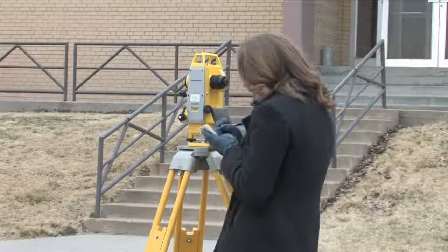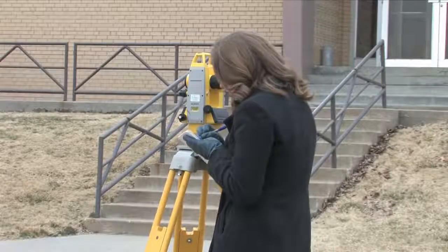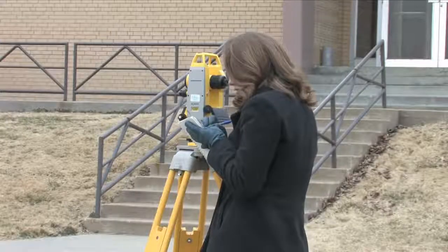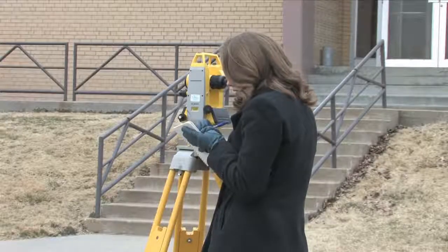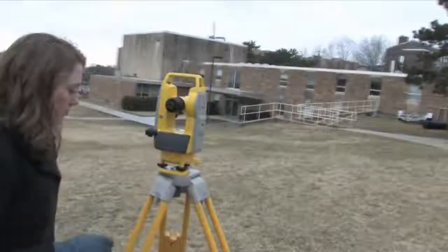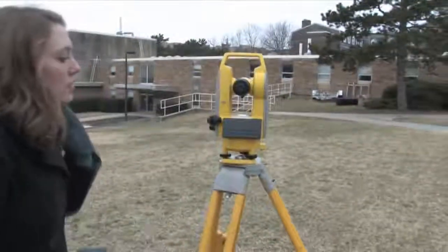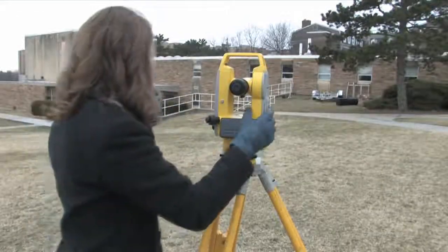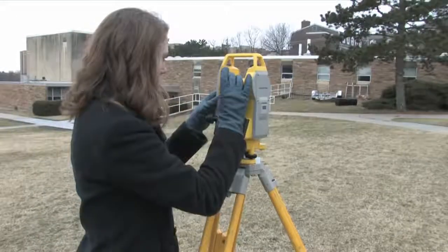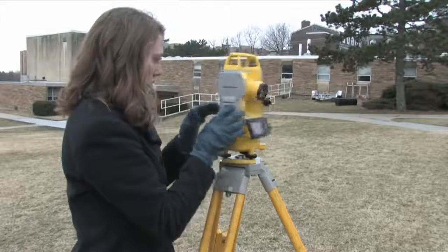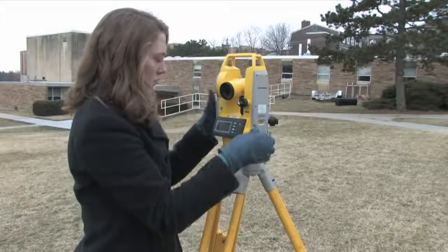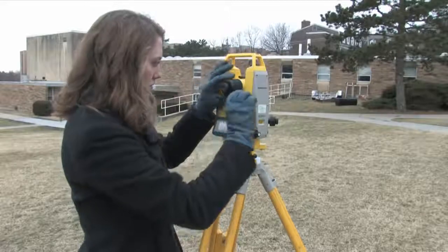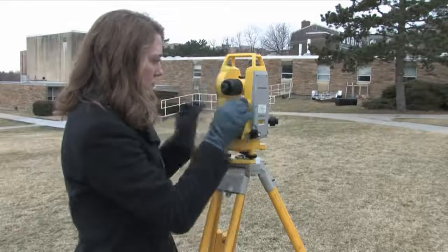To further reduce error, the survey team may turn this angle a third time, a fourth time, plunging the angle alternatingly just as we did between the first and second angle. This should always be done in pairs so that there is an even number of angle turns. Bear in mind also that once the instrument has turned 360 degrees, it will revert back to 0, so you may have to add multiples of 360 onto your horizontal angle to ascertain the correct angle reading.